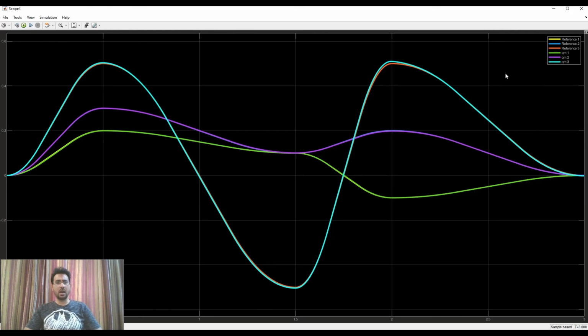If you increase the Kp and Kd more, the torque output is going to increase and these trajectories will be followed much more strictly. If your robot needs to move at higher speed and operate with high accelerations and decelerations, then the values of Kp and Kd have to be much larger. So dear learners, I hope you have understood what the computed torque controller is, and now you can easily implement this controller in your MATLAB and simulate your robot.